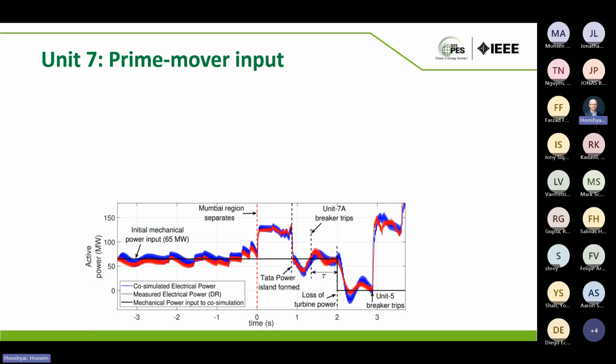So we started off with an initial guess, and gradually, to keep the discussion brief, I did not put all the initial waveforms. But since I have already given you the description that the turbine input is coming from the waste heat from another generator, we understand that after that generator tripped, its waste heat supply will also stop after some time. So we assume that the prime mover input to this generator will be reduced after a time. So we were trying to optimize that delay.